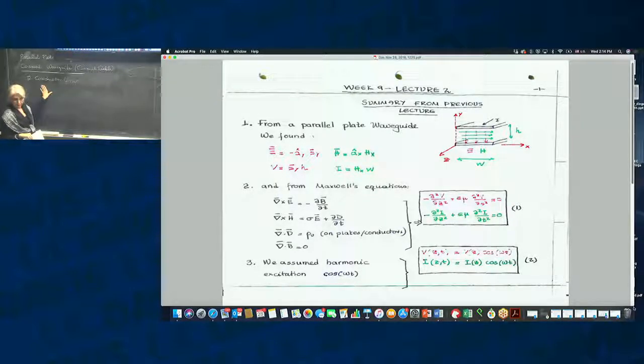All right, and in two conductor lines or waveguides, the characteristic is that if the frequency is low enough, if those geometries have a cross-section which is much smaller than the wavelength, so size of cross-section, each of the dimensions, so each dimension, not just a product or something, not an area, but each of the dimensions are much smaller than the wavelength, these two conductor lines create transverse electric magnetic waves.